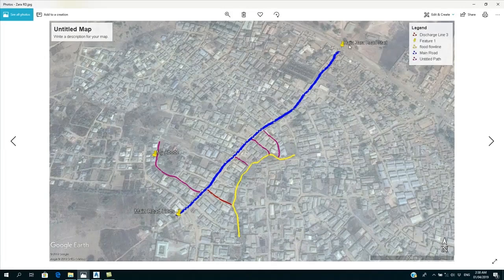You can see we have this road extension of 1 kilometer. There are some offshoot access roads, and you also have the feature lines for the flood flow lines. That means this road will have drainage facilities because of the slope, and this drainage will be diverted at these brown locations to take it to the stream level of the water in these directions.